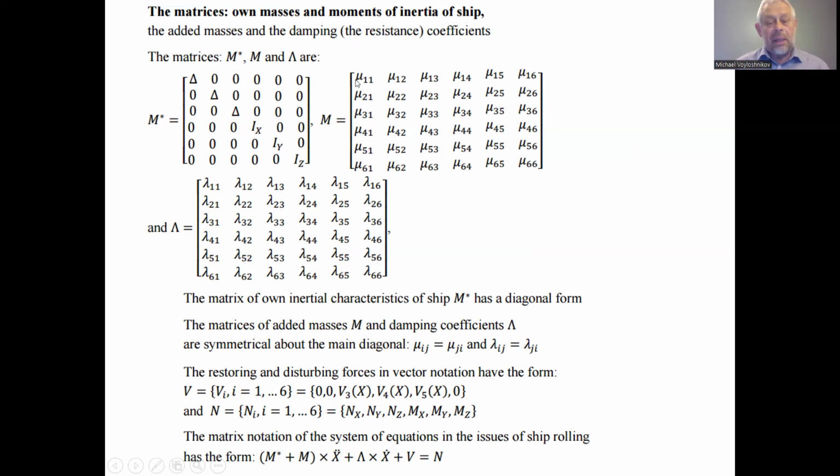This is the added mass of water in the ship motion, impacting the forces of inertia of the ship in motion along the abscissa axis, characteristic 1, translational motion. So displacements are characteristics of the inertia of the ship in translational motion,